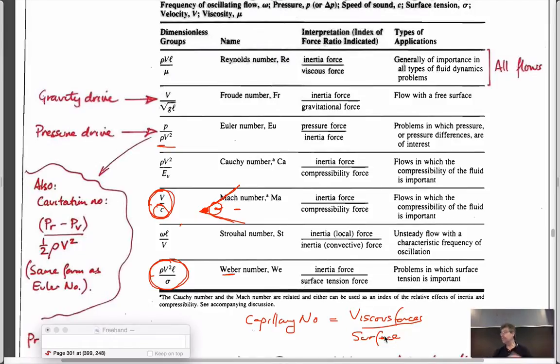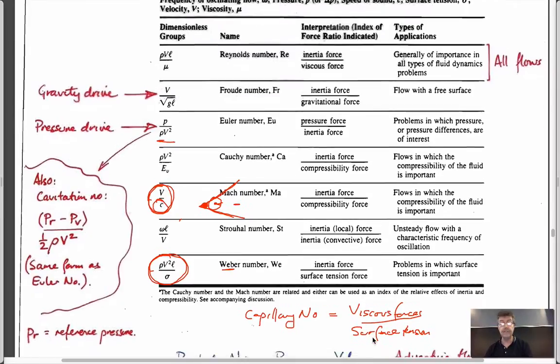So in other words, if you're trying to push oil through a reservoir through the pore throats, the resistance to flow is by viscosity because it drags against the side of the pore throats. But also the other impact is that you have bubbles of oil and bubbles of gas or bubbles of water in the system, which have an interface with each other. They don't mix with each other. They're immiscible. And so to move components through reservoirs, you have to be able to overcome surface tension forces. And so in very fine-grained materials, it's tough to be able to push things through them because the surface tension forces become very large compared to the viscous forces, and you can't.